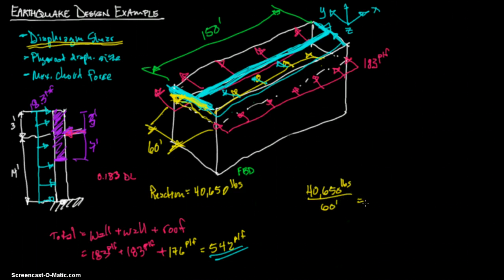And you select the plywood diaphragm from the UBC table 23-I-J-1, and it's on page 98, which I need to go find. But let's figure out what this is. 4,650 divided by 60 equals 77.5, and that's pounds per linear foot.